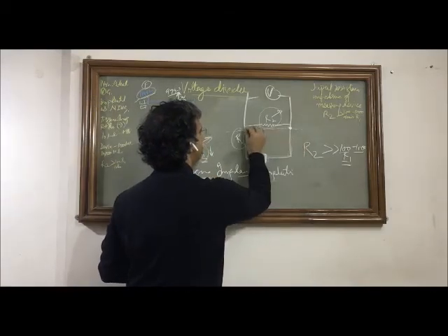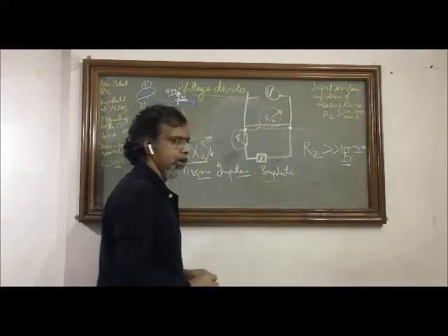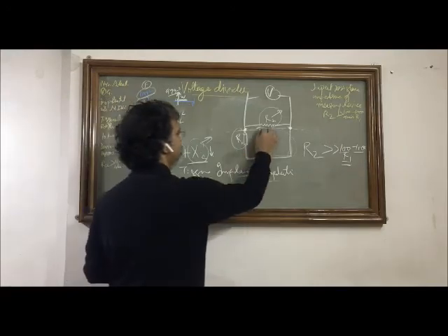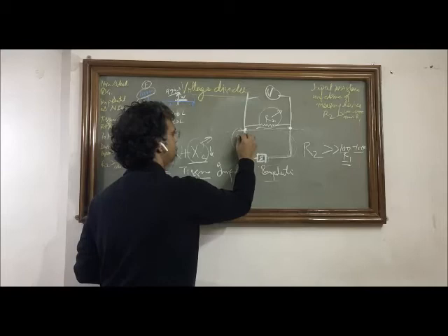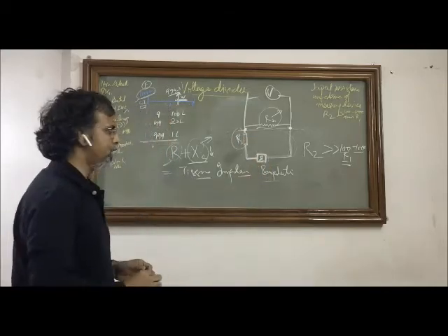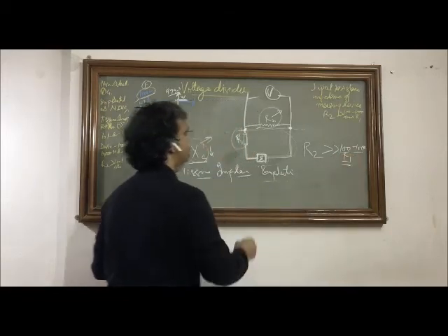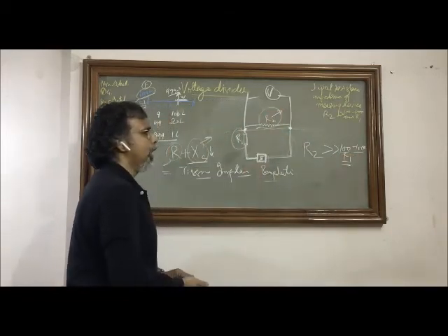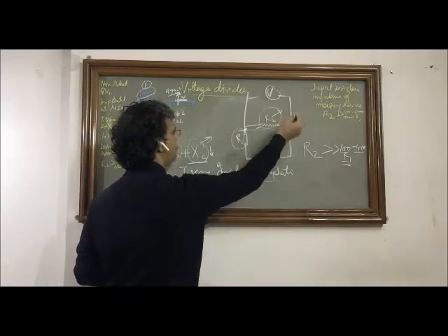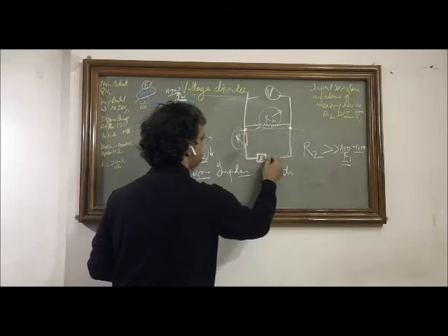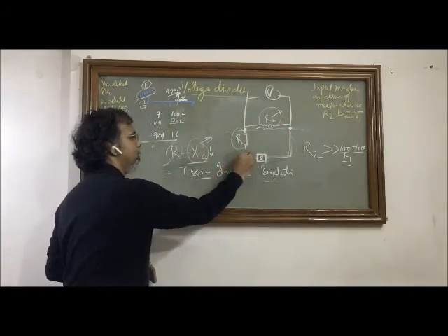Now after this, when it comes to these 2 points, that is the skin surface, if we apply a measuring device and make the resistance of that measuring device very high compared to the internal resistance of this biopotential generator, in the tune of 100 to 1000 times higher, the resistance of the measuring device is going to be 100 to 1000 times higher than the internal resistance of the biopotential or the tissue impedance.